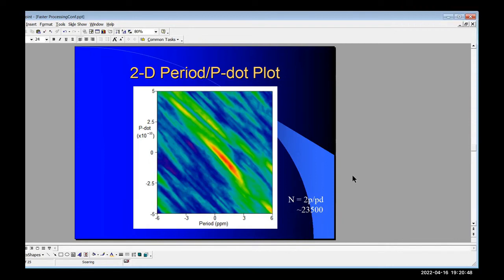Actually, Peter, I have a question in that regard. The radio astronomy band, which is notionally NTSC channel 37, I thought that was reserved for radio astronomy only in ITU region 2, which does not include the UK. So does the UK have their own reservation for radio astronomy in that band? Yes, 608 to 614. Yeah, 614. That's NTSC channel 37. Yeah, at 615, 616 we've got TV stations, but the filters I use are very sharp.